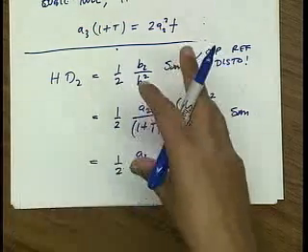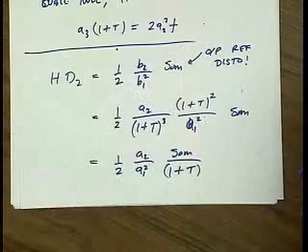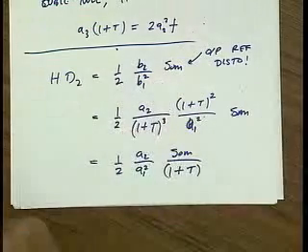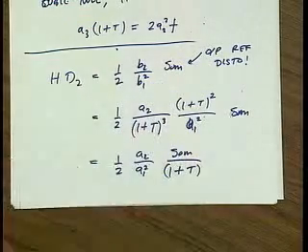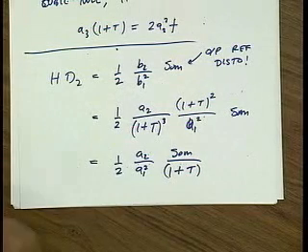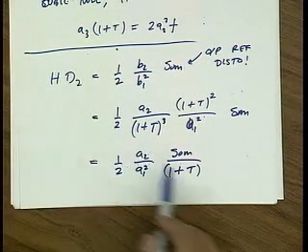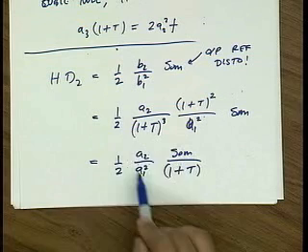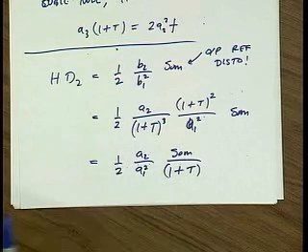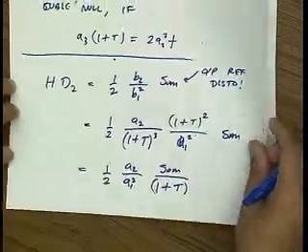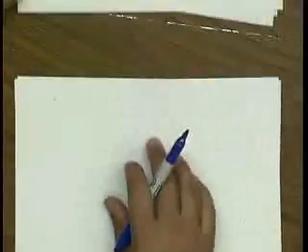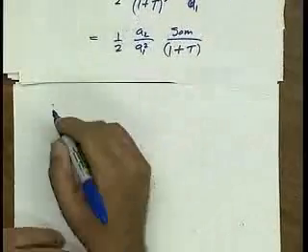I can't compare my original amplifier to the one with the feedback because the original amplifier had more gain. I've killed that gain by putting feedback in. But even though I did that, I still have improvement. The output referred HD3 gets better. Okay, very good. All right, so that's HD2, let's look at HD3.